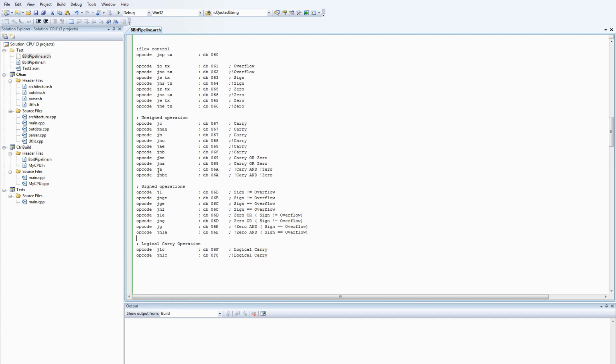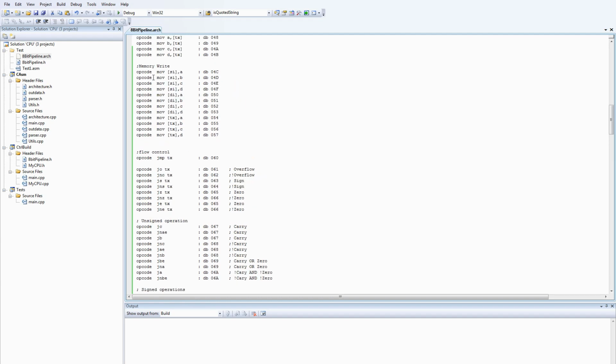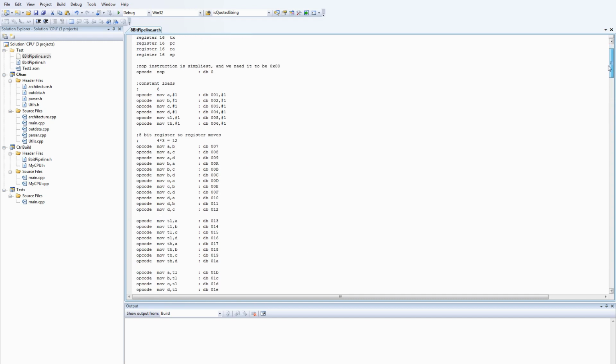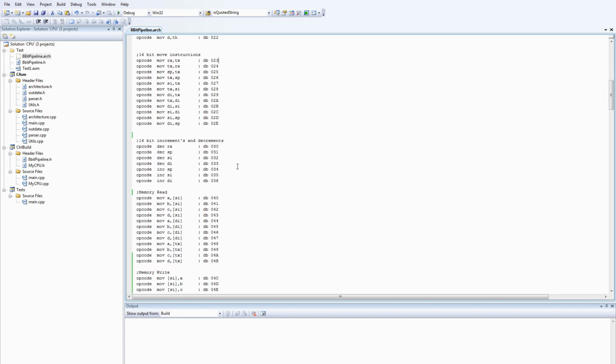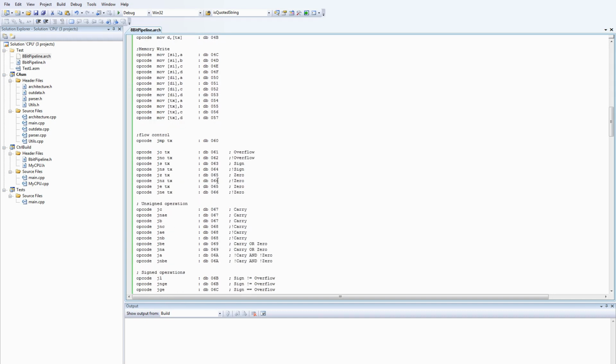So when it sees a line of assembler, it comes in to here and it pattern matches against these options. So you declare your registers at the top and a few other basic things. And so if it comes across the instruction mov ra, tx, it will come down here, and then the material after the colon is what it's going to emit into the instruction stream. Now I'm gradually evolving this assembler, but it's still quite early days yet. But for simple processor architectures like this, it does allow you to add instructions to the assembler very, very easily.